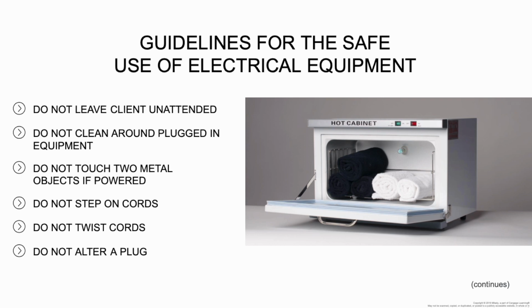So guidelines for the safe use of electrical equipment continued. Avoiding contact for both you and your client with water and metal surfaces so that you don't electrocute yourself or them. Keep your electrical cords off the floor as much as possible, especially in areas where walking is paramount. Do not leave your client unattended while the client is connected to an electrical device. Do not attempt to clean around electrical outlets while equipment is plugged in. Do not touch two metal objects at the same time if either is connected. Do not step on or place objects on electrical cords.